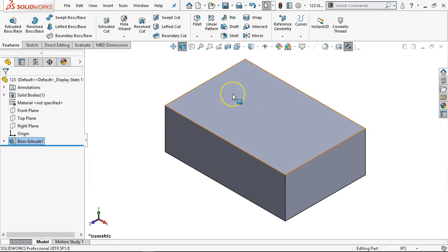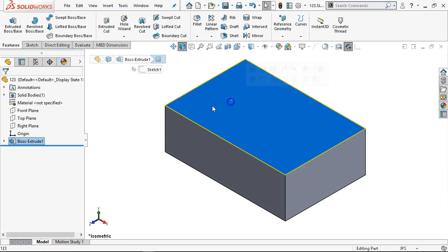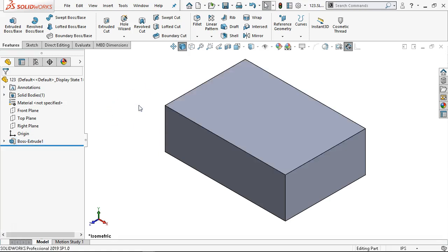All right. So once that's created, now we have an object with features. So one surface, and the conditions that we would want to pick for setting up the form and the datums is what's going to be the most accessible, what's going to be the visible items out of this group. So to start off with, everybody can approach the drawing or work within the template. Where this gets a little more involved is when we go over to model-based definition, DimXpert, and then taking it a step further, as we build up into assemblies, going into tolerance analysis.